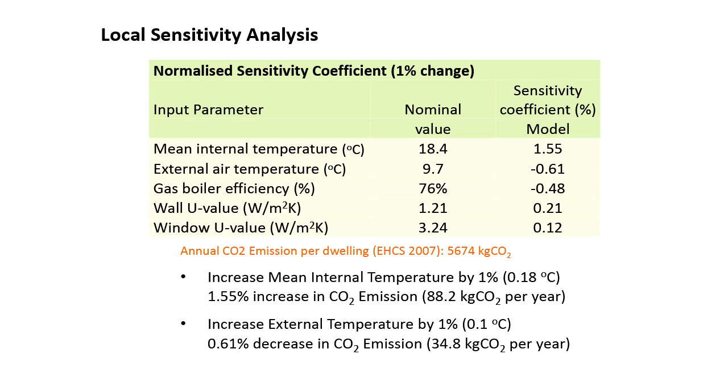So the most sensitive parameter with respect to our building stock is the occupant's choice about the temperature of their house. And if you imagine, 35 years ago, the average household temperature in the UK was 12 degrees, the average, so including the bedrooms that were usually unheated and the living room. Now the average household temperature in the UK is about 19 degrees. That's a major increase in thermal expectation and a major increase in energy demand. It's effectively doubling the energy demand if everything else remains the same. So the biggest single parameter, from our work at least, is occupant behavior and occupant expectation with respect to comfort. The other parameters are less sensitive, and I won't discuss them in any detail here.